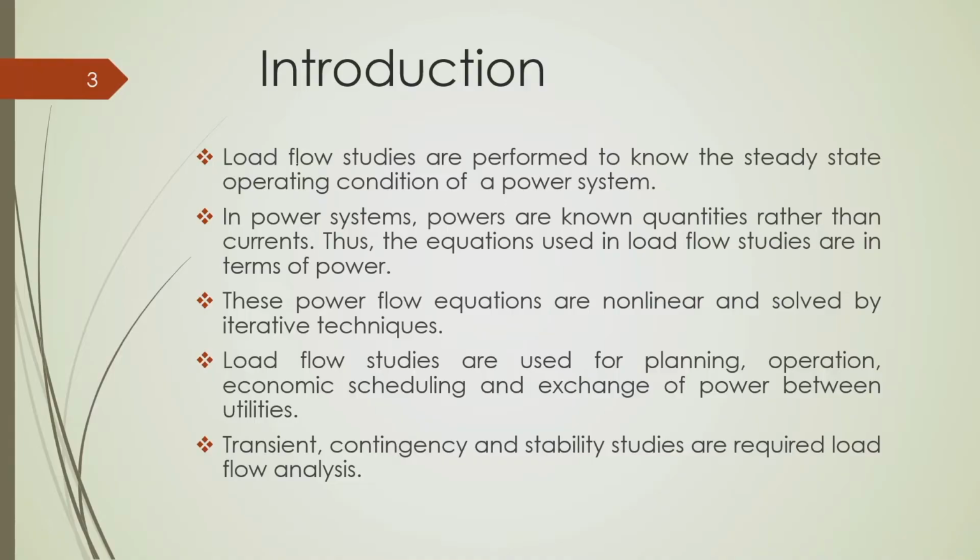Now, as I said, load flow studies are performed to know the steady state operating condition of a power system, and that is why it is an important tool for any type of power system problem, as well as the distribution system problem. In a power system, power is the known quantity rather than the currents.